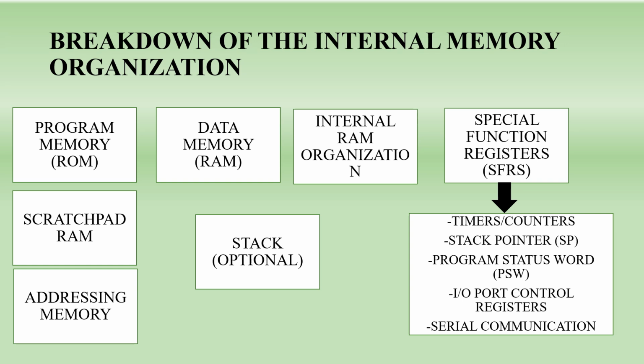The stack is optional, it is not needed for each and every internal organization, but 8051 has a stack. Here the stack is a last in first out data structure, LIFO, using push and pop operations. It is used for calling subroutines and temporarily stored data, and it also uses the stack pointer register to keep track that it is always pointing to the top of the stack.